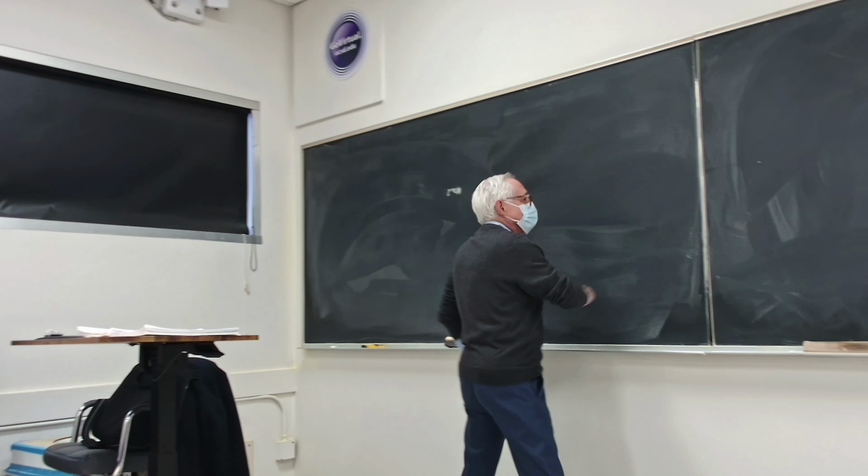Velocities, if we know the velocities, fine. But for superheated steam, these terms are so small compared to the h in and h exit. Okay? So practically you have m dot in h in minus m dot exit h exit, W dot control volume, if this is non-zero, and Q dot control volume equal to 0. Same equation we use therefore for it. Okay? So, mind you, it can be a gas turbine or a steam turbine. Okay? A gas turbine, therefore, air in a jet engine.